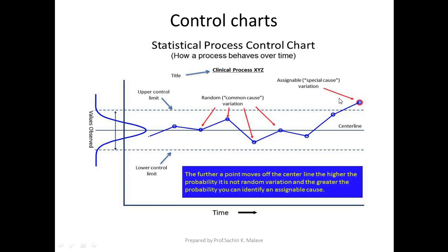So 180 plus 10 BHN means the upper control limit is 190 BHN. The lower control limit will be 180 minus 10, that is 170 BHN, isn't it? So the lower control limit is 170 BHN and the upper control limit is 190 BHN. Whenever you are checking the actual hardness of a component, whatever value is there, you have to mention it. That scale will be provided here.